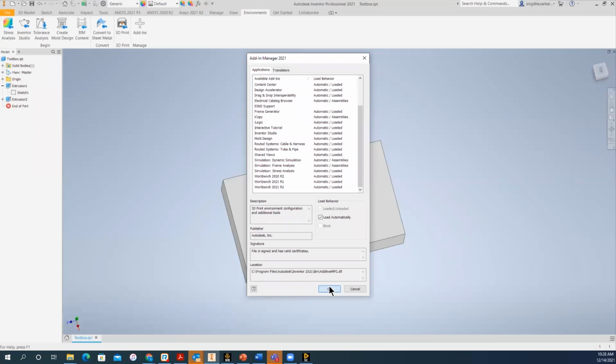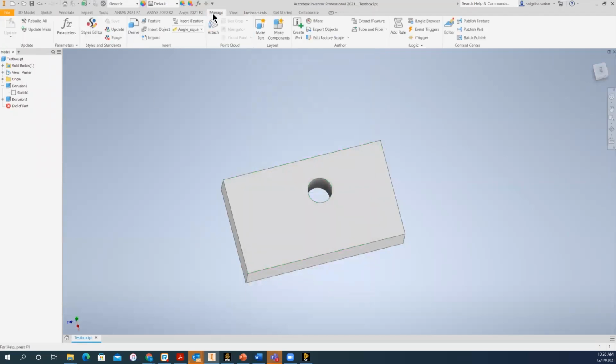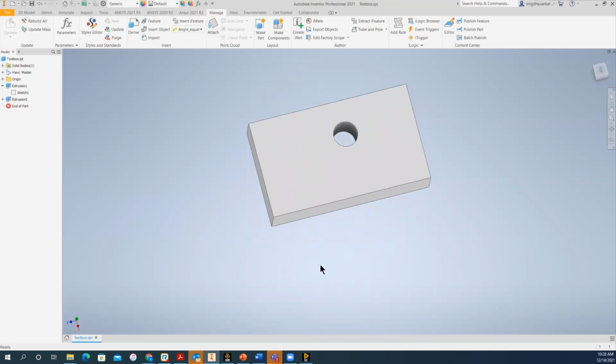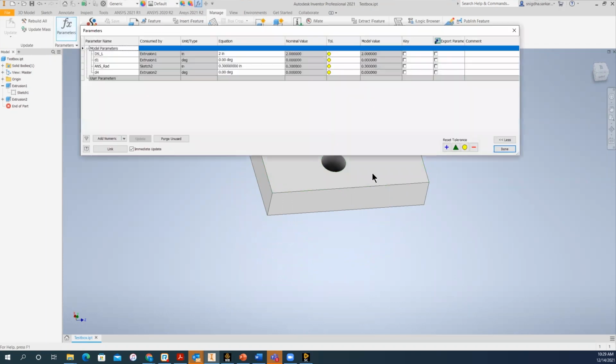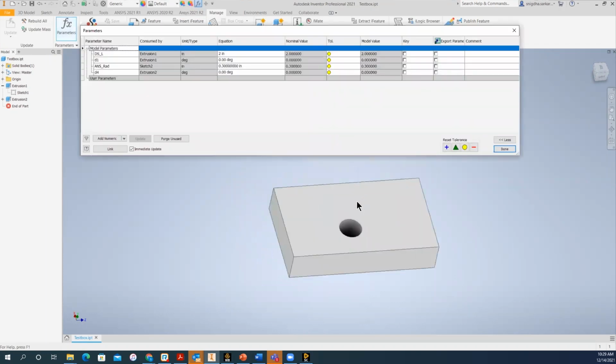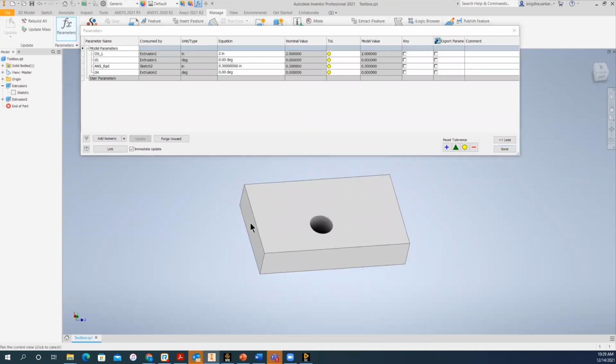So I have an example geometry over here. Okay, nothing crazy. In fact, this is pretty similar to what I created in SpaceClaim. And I have certain geometric parameters associated with this design. So one is the length of the extrusion. I just created a sketch plane and then extruded it by some length. So this is basically the length of the geometry. And then I have another dimension for the radius of this circular face over here. So I created that as a second sketch and then assigned it as a parameter over here.